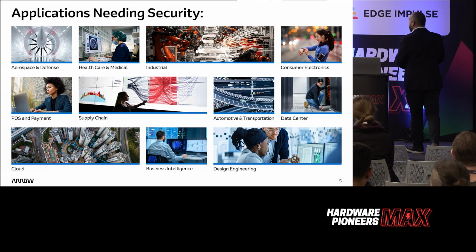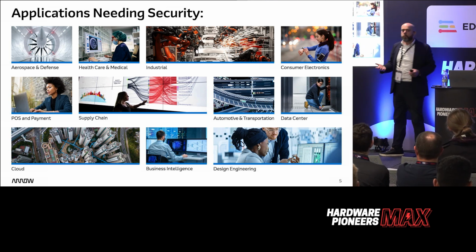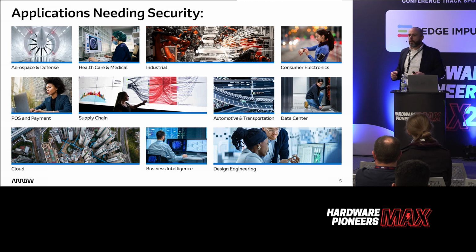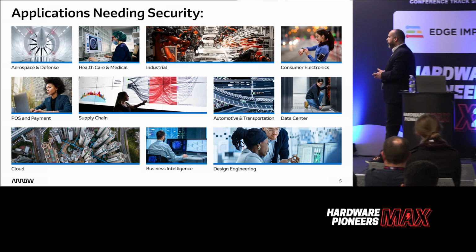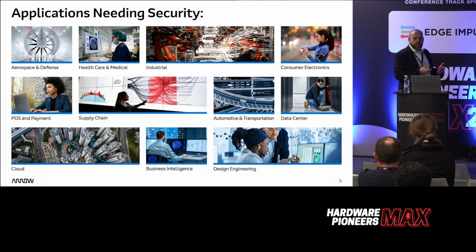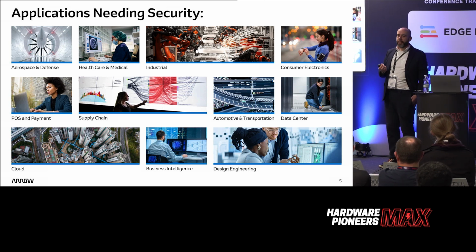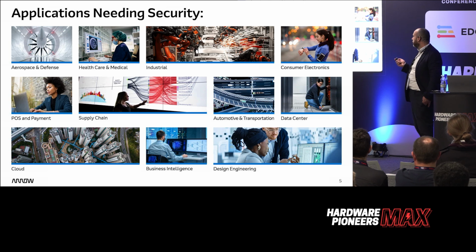So I think most of us were kind of expecting that it would be consumer electronics. That's where most people are thinking the CRA applies. But if you design anything with a microcontroller, a microprocessor, GPU, MPU, FPGA, the chances are it could be classed as connected, so please do check.